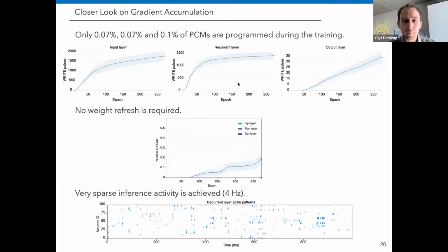One of the problems you can usually get with this kind of differential configuration, where two devices represent the synapse, one with positive and one with negative conductance, is this: if you increase one conductance and also increase the other conductance, because this corresponds to decreasing, while the first corresponds to increasing the synaptic conductance, at some point your weights will saturate.